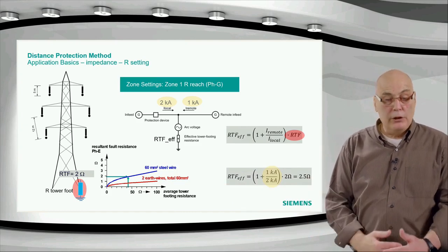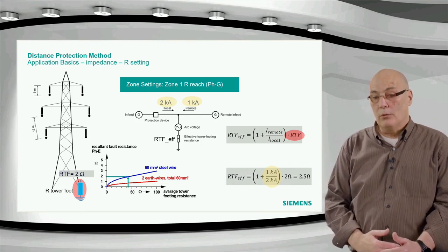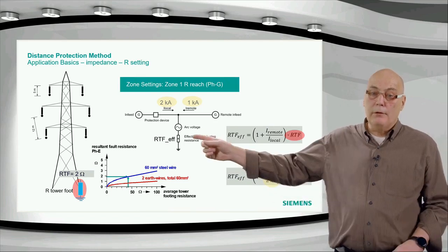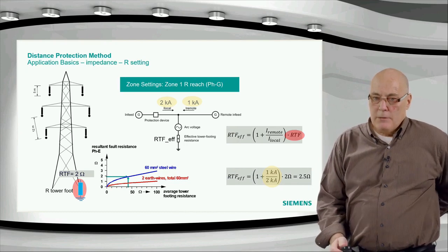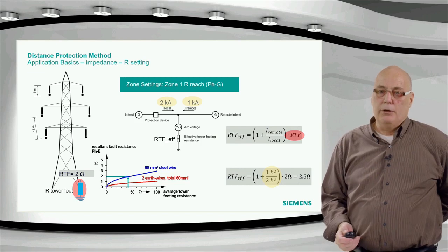Sometimes we get sequential tripping, teleprotection arrangement, and so on. We must assume that you need a weak infeed logic also for that function. That sometimes the weak infeed side will have difficulty getting effective resistance coverage. That's one of the aspects why we have a weak infeed logic or weak infeed function in the teleprotection later on today.